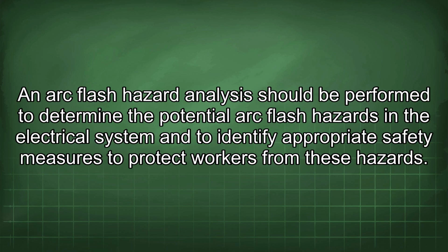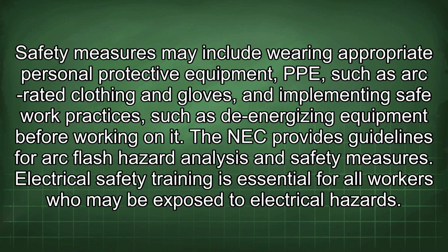An arc flash hazard analysis should be performed to determine the potential arc flash hazards in the electrical system and to identify appropriate safety measures to protect workers from these hazards. Safety measures may include wearing appropriate personal protective equipment, PPE, such as arc-rated clothing and gloves, and implementing safe work practices, such as de-energizing equipment before working on it. The NEC provides guidelines for arc flash hazard analysis and safety measures.